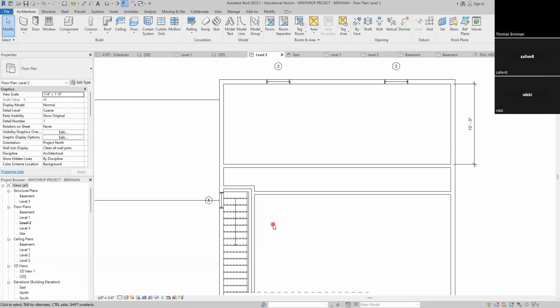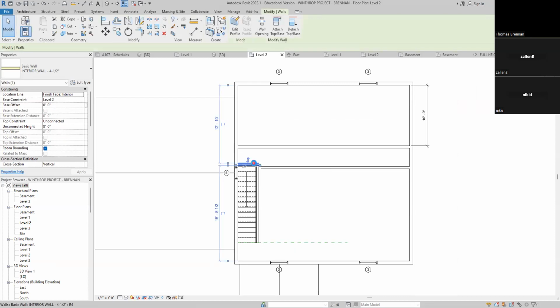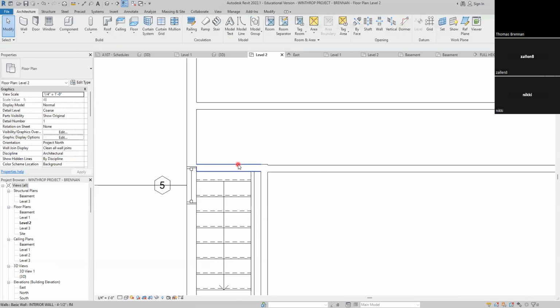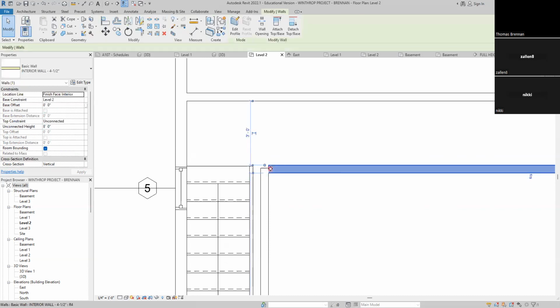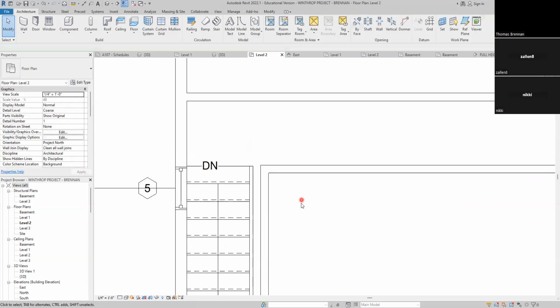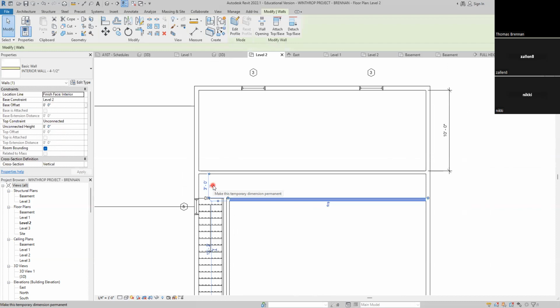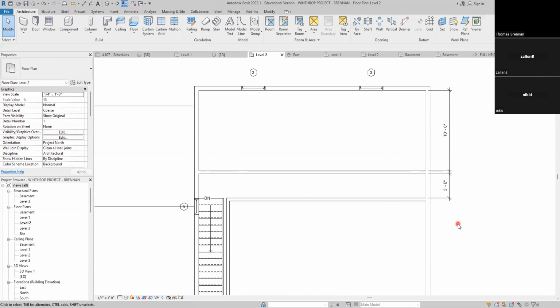And then it's not quite connected. It needs to be straight across. So what I'm going to do right here is a couple things. First of all, I'm going to take this and I'm just going to back this up a little bit here till those are kind of joined together like that. Just going to go ahead and do that. Actually, it doesn't need to even do that, does it? It should be pretty even with that. 3 feet. Let's go ahead and do this. Let me get rid of that part of the wall. And I'm just going to take this and drag it over here so the two are like that. And it should be basically like that. So now when I click on there, that's a 3 foot hall. Okay, so we got that. So I'm going to take this and drag this down like that. Does that make sense so far?